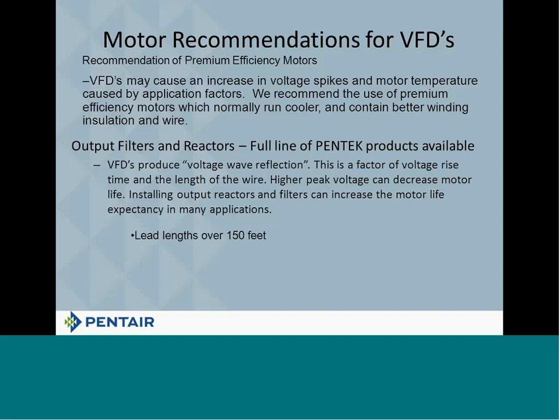All right? So when do we need a filter or reactor? If your lead length, in other words, from the drive to the motor, is over 150 feet. If the cost replacement to change the motor out is prohibitive, typically that happens around 30 to 40 horsepower, and we begin to say, geez, you know what, at 40 horsepower, I can almost rewind the motor cheaper than I can buy a new one.